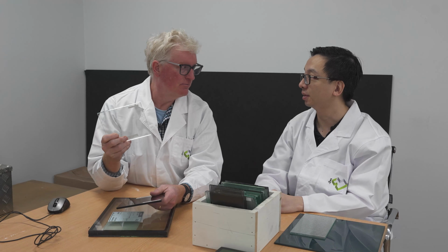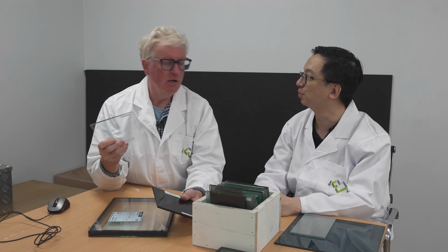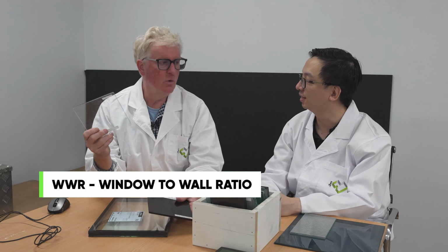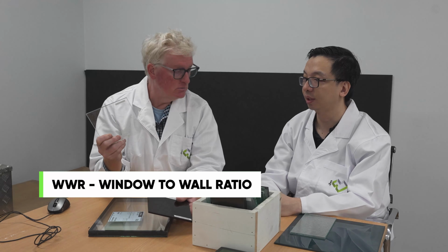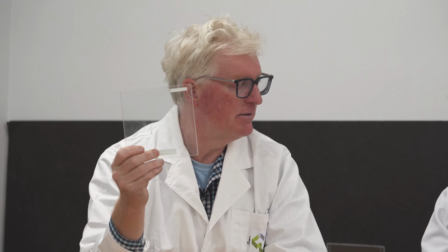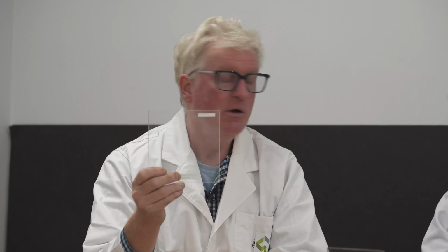If we have a small window to wall ratio, we call it, a small window aperture, let's say 30% or less of our wall is glass, we would want the glass to be more on the clear side, allowing as much visible light as possible to come through. So a high visible transmittance.